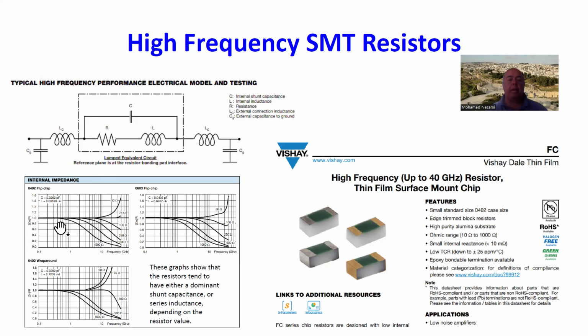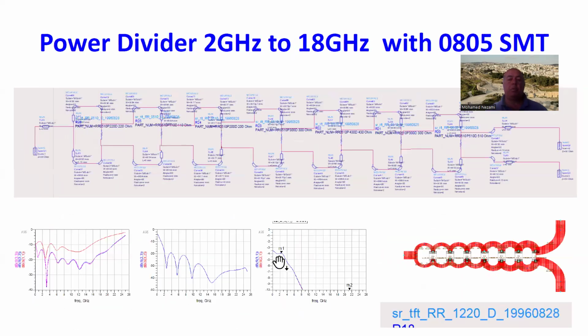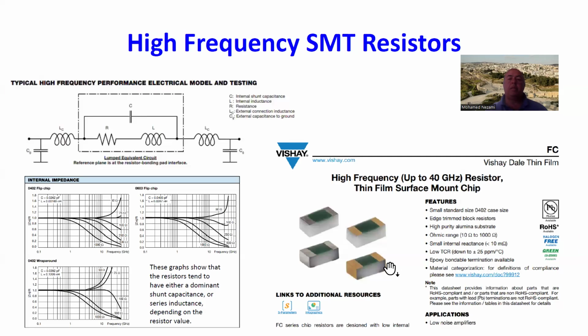And then beyond that, it's really going to behave depending on the resistor value. It's going to be dominantly inductive or capacitive, and that's due to these parasitic things in here. That's really what made this deteriorate, because you're trying to get these surface mount 0805 packages to work up in these frequency regions, okay? And so we get an issue with this.